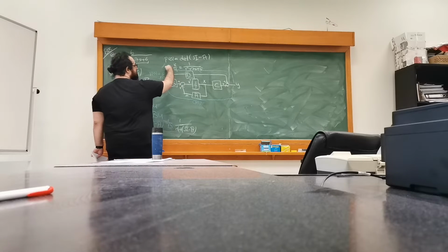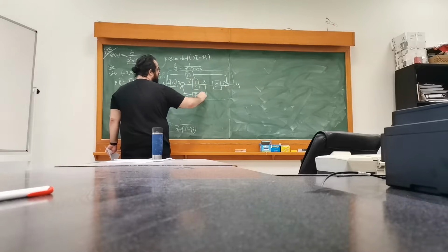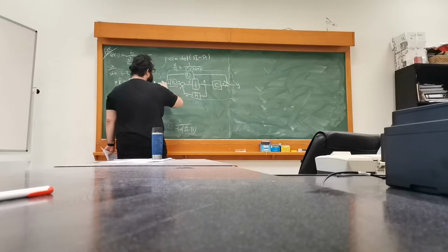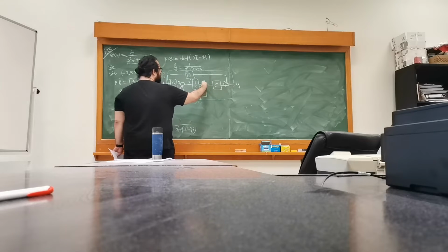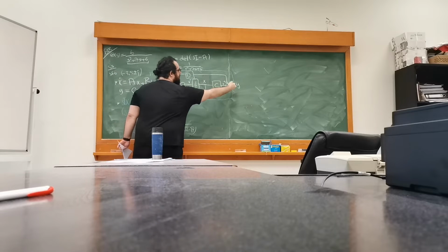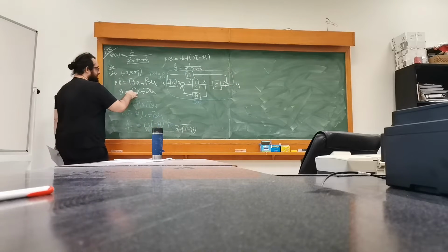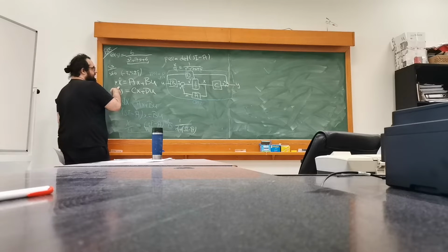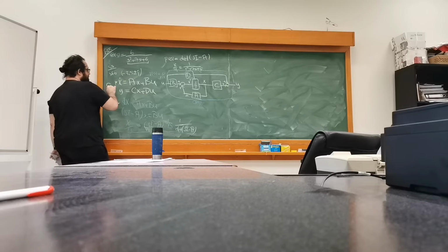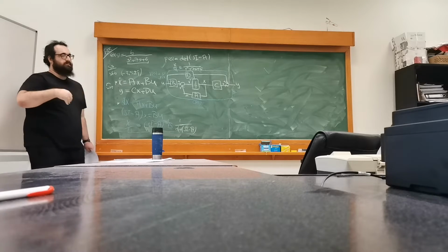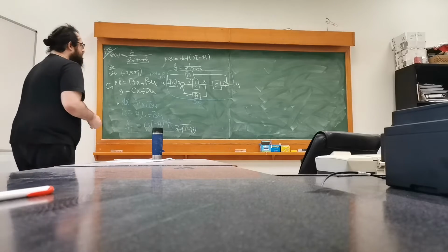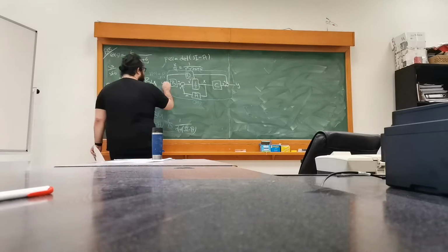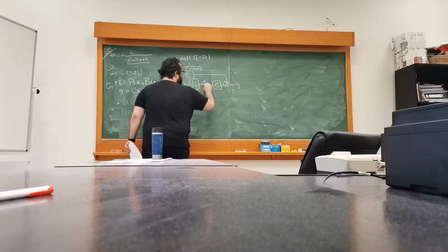Now this first equation here is just about this dynamic part. Once I have that, I've generated from the input the state itself, then I can work out what the output relation should be, because it uses the linear combination of the x's and the input in order to generate my output vector. Therefore, I have this model Cx plus Du that gives me the output. But the dynamic part is here. I have n integrators, because x is n by 1 and each of them needs an integrator. So therefore, I'm modeling from input to the state, not further.